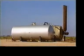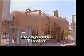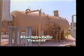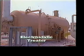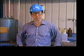Two other separation methods involve mechanical devices and electricity. Mechanical devices, such as gun barrels and free water knockouts, utilize gravity to separate oil and water. Electrostatic treaters use electricity in conjunction with heat and chemicals to separate oil and water. Now, we will discuss electrostatic treaters in sections 2 and 3. Those are the most common methods of emulsion treatment used today. To find out which methods are used in your area, ask your supervisor.